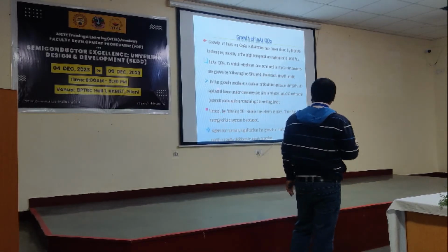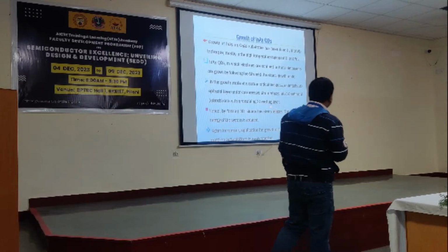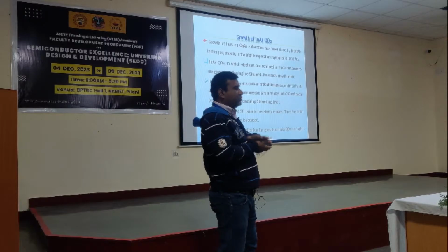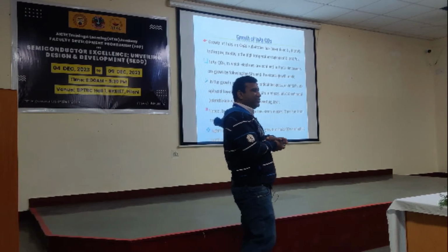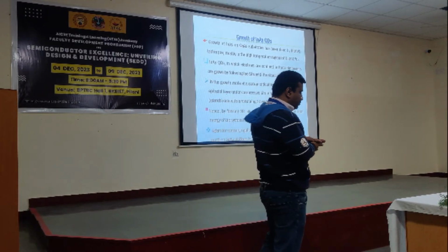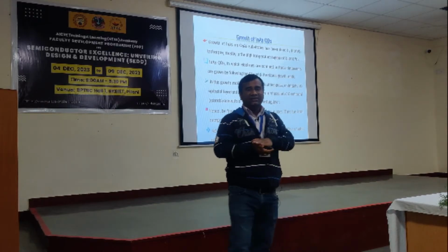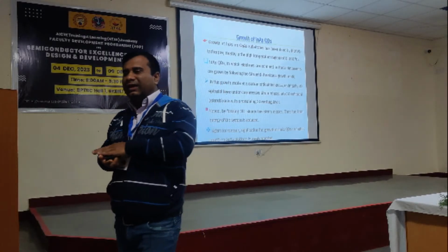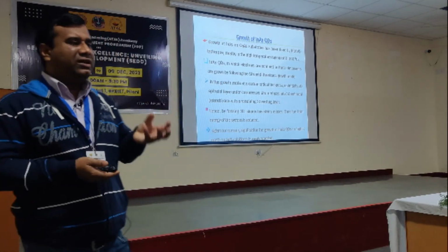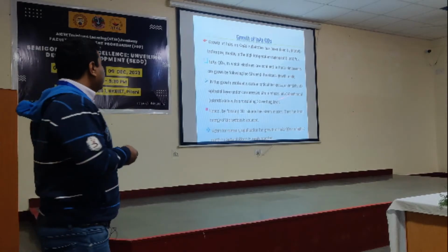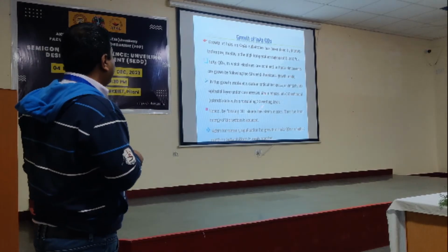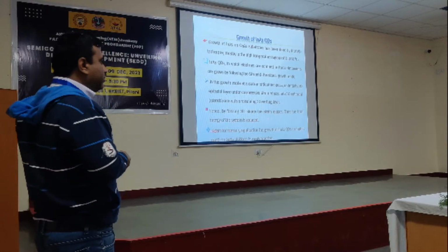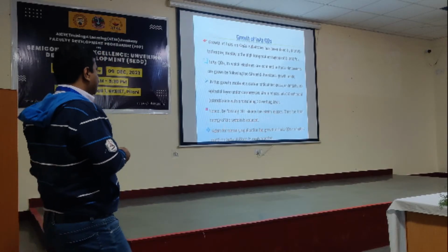Hence, in this growth mode, at a certain critical thickness, initially your 2D thin film will be grown. That grown 2D thin film is actually under high stress, and after relaxation or minimization of surface energy, that thin film will relax into 3D islands, that is, 3D quantum dots. Hence, by forming these quantum dots, the strain will be relaxed and the total energy of the system will be reduced or minimized.